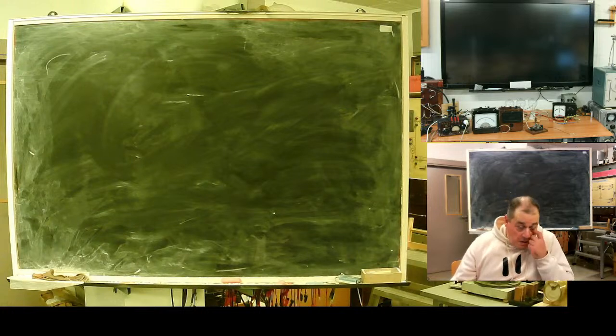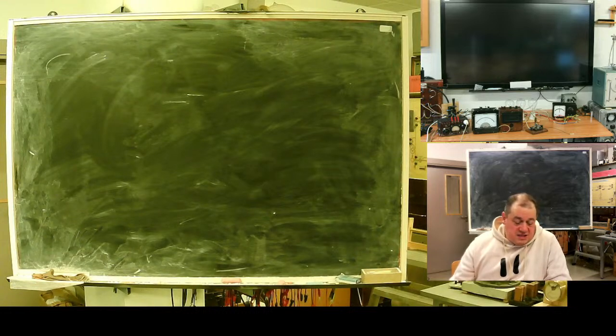Bad magnetic conductivity means very low inductance, very low resistance. So this machine possibly will have much smaller resistance in the zero sequence network.